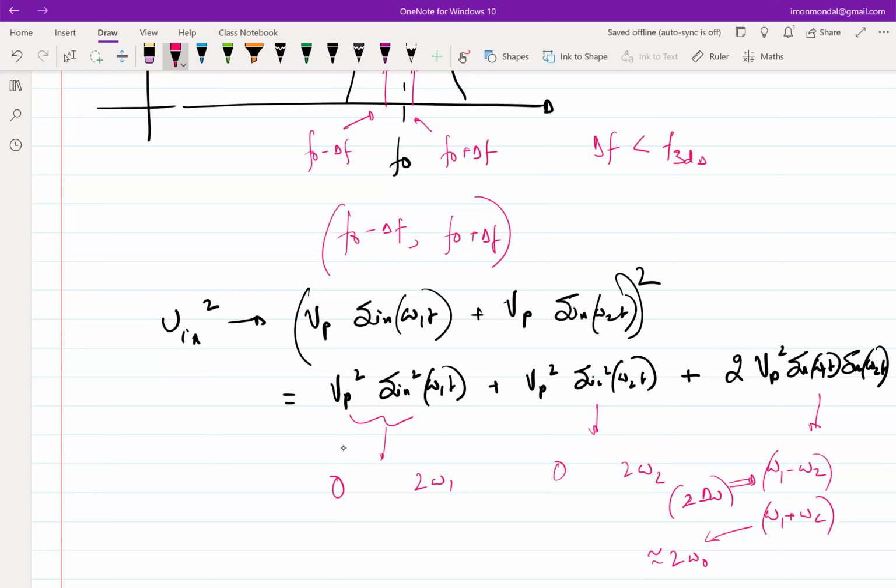So before I move on, if I say it's not a problem, it's not strictly true. So clearly there is an issue with some things falling back on DC, right? And the amount of signal that falls back on DC is also proportional to VP. So the larger the VP, it looks like it adds to the DC offset. You set the bias with some value, right? When you have to bias an amplifier, you have to give some DC bias.